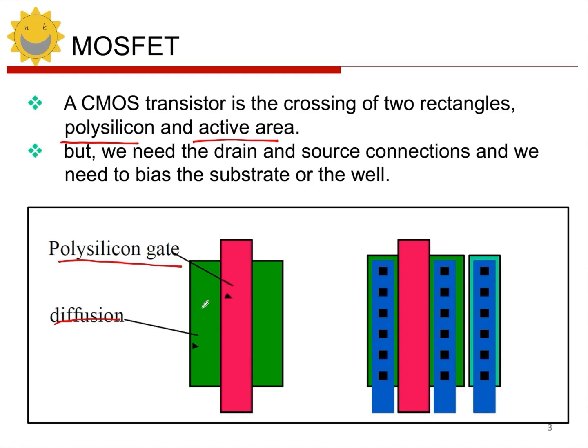After that, we need to connect its source and drain. We have been emphasizing that a MOSFET is a four-terminal device, so it's crucial to pay attention to its substrate connection. Therefore, we need to connect its source, drain, and gate first. After interconnection, you must pay attention to its substrate, or body.